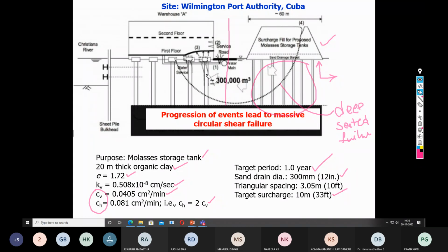So this was the first observation. He did not anticipate the thrust in the lateral direction because of the vertical load. Because of this thrust, there is an excess lateral pressure on the pile foundation, as you can see here. There are two things. First of all, this pile foundation was not designed for such lateral load. Second, the engineer who designed the sand column did not anticipate the possibility of lateral earth pressure. Because of these two things, there was a huge litigation that went on. This person has sued this person, and so on and so forth.